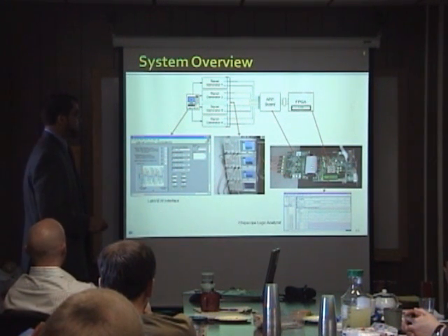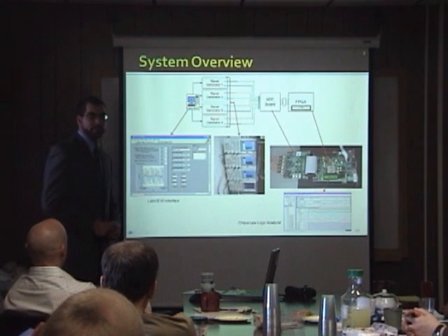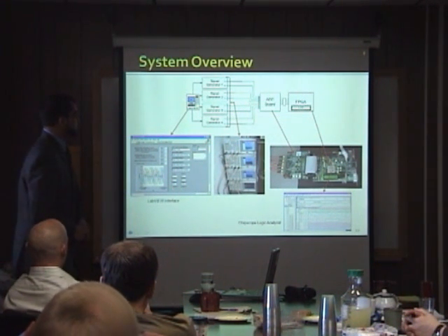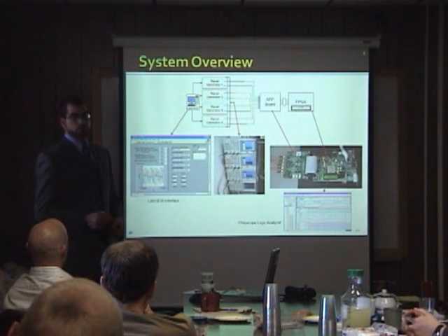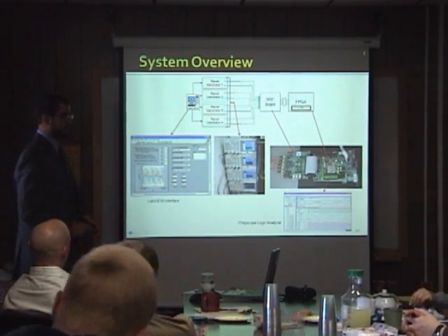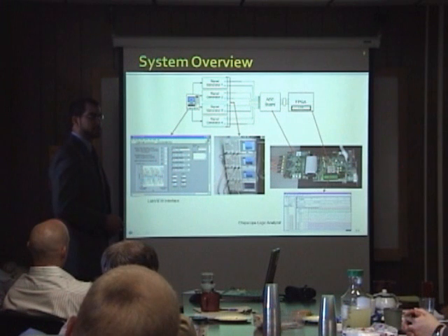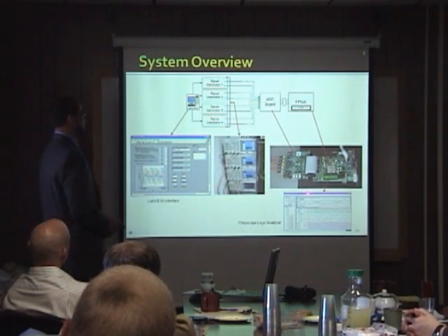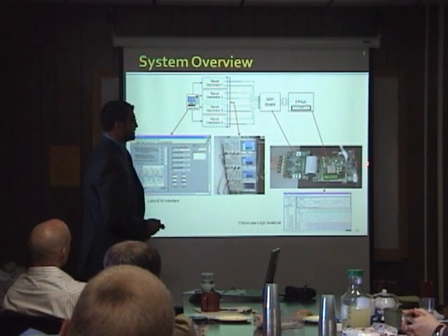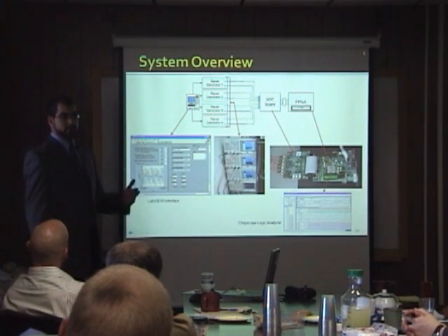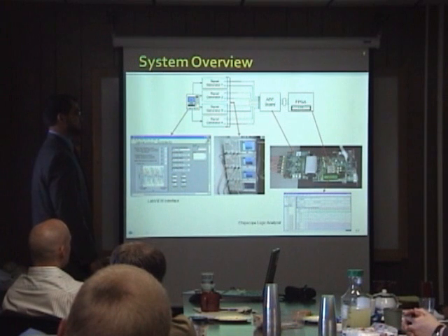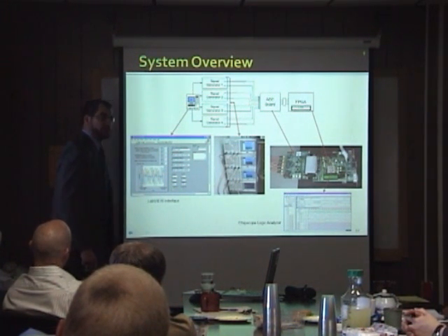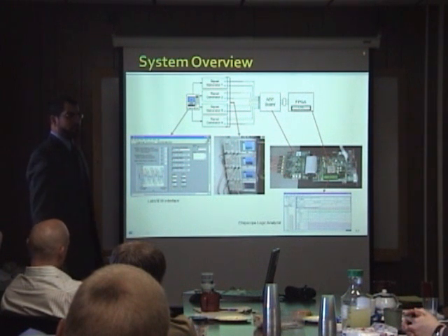The ADC board, of course, is responsible for sampling these signals. It currently operates at 2 rates, configurable in real time: 12.5 megasamples per second, as well as 25 megasamples per second. It's configurable through bit switches in the FPGA. You can pick whichever sampling speed. Currently, we use it only at 25 since we're more interested in the higher sampling speed to hit the WiMAX radio bandwidth.